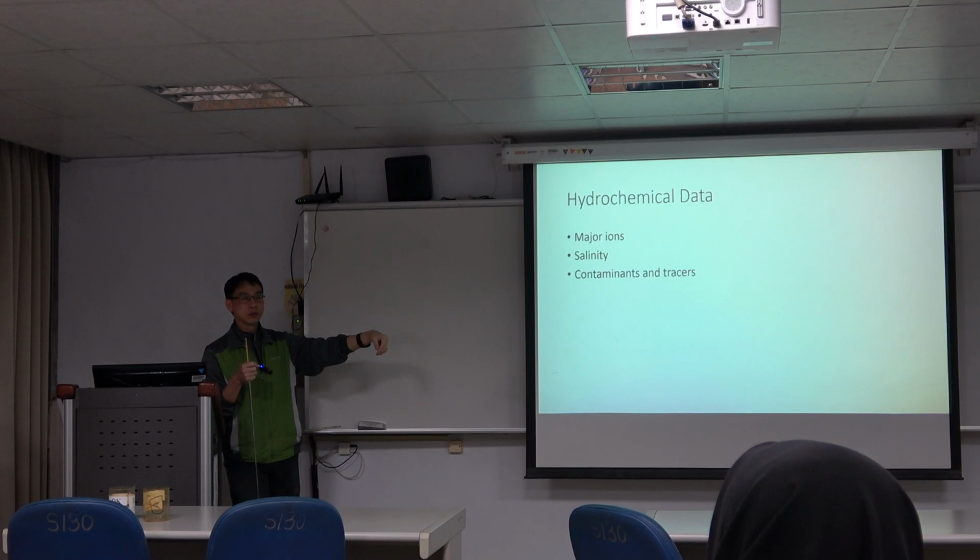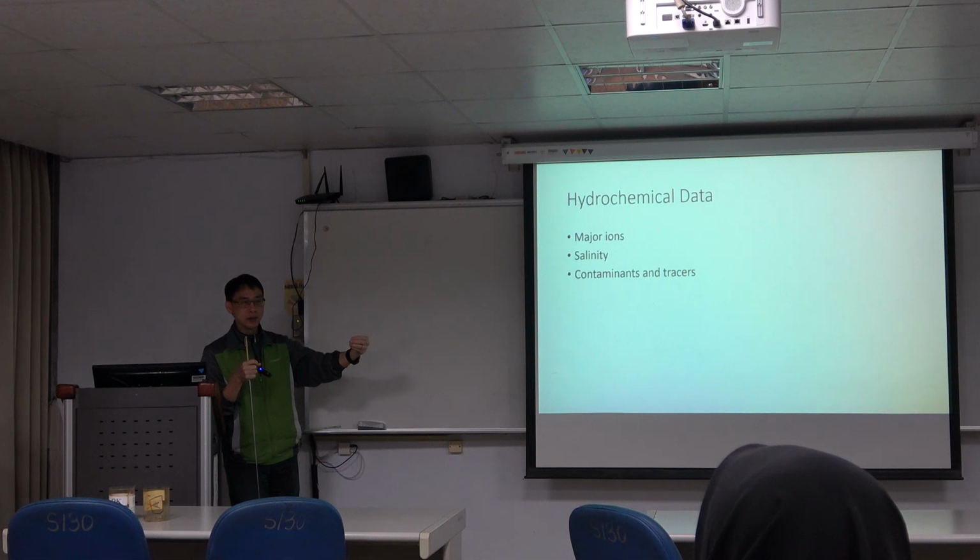And we don't want the cool water moving too fast to our production wells, because it becomes like a cooling front. Your temperatures will decrease, and you will not be able to run your geothermal system. So we hope the water moves slowly, and then it can be heated up again and come back here, and it becomes a loop.